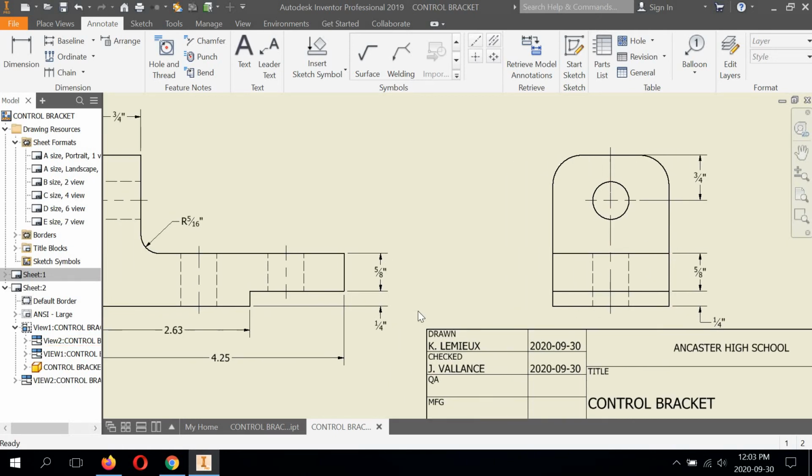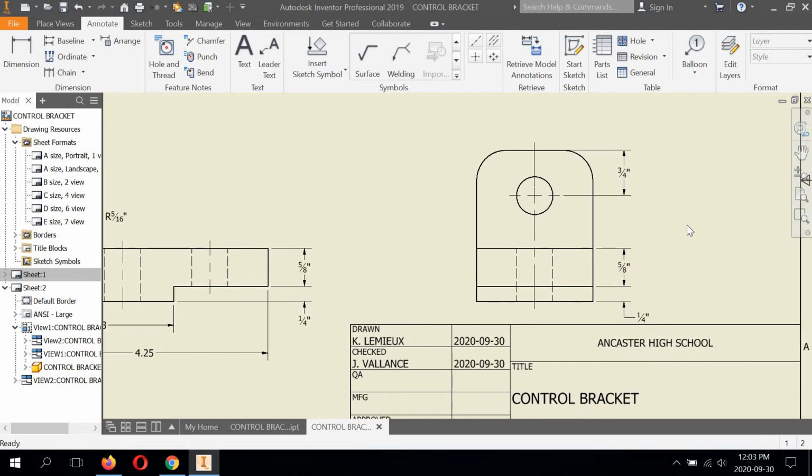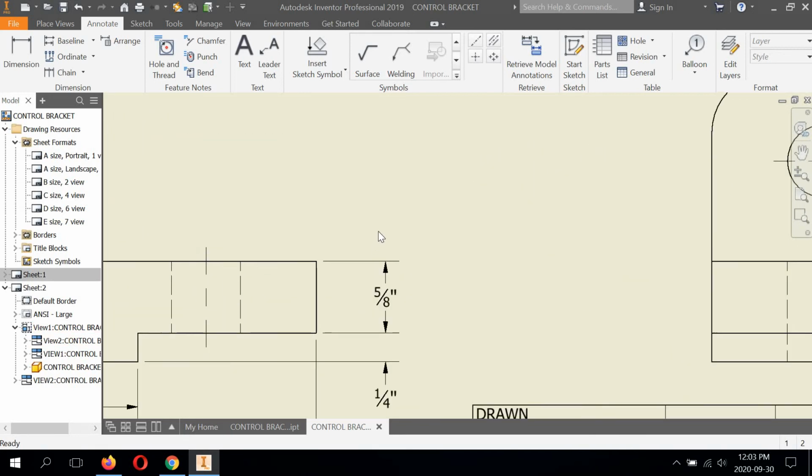And again, we're dimensioning between two views, but this is okay if there's an advantage. And I think there is an advantage to have these dimensions shown here on the front view than here. So we are going to drop these dimensions here because that's over dimensioning. We're going to keep them on the view that they look the best, and we're going to move on from here.